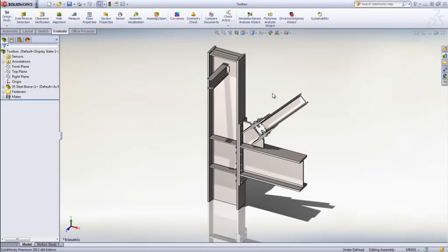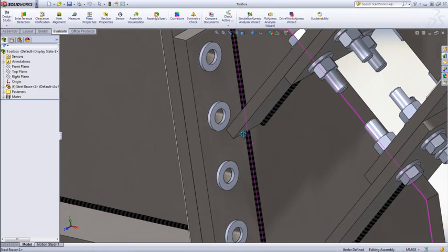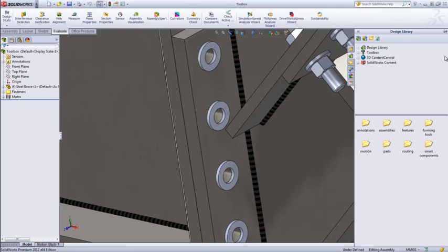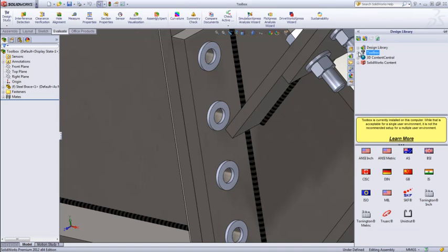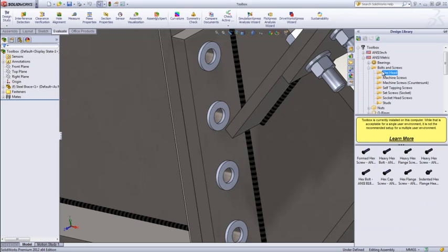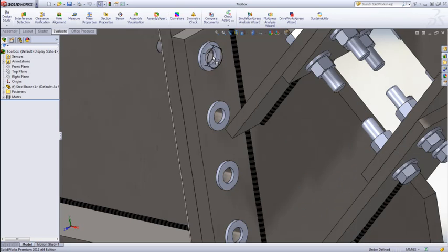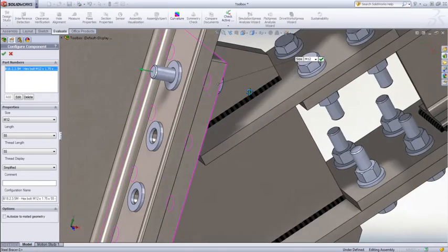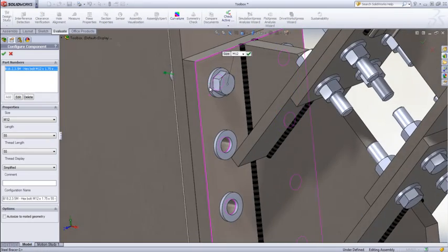In SolidWorks 2012, the toolbox has been re-architectured, removing the reliance on the Access database. No longer does SolidWorks need to load or read from a huge database that contains all of the standard, size and property information for each toolbox item. This means that toolbox items work much faster and are more portable than in previous releases. All data for sizes, standards and properties are contained within each file.